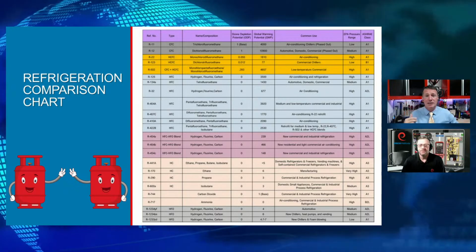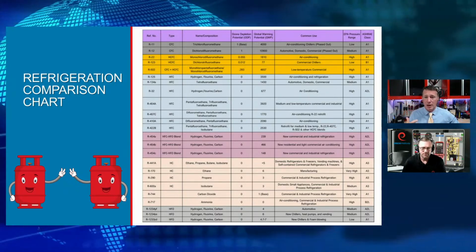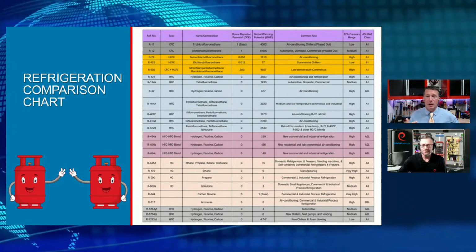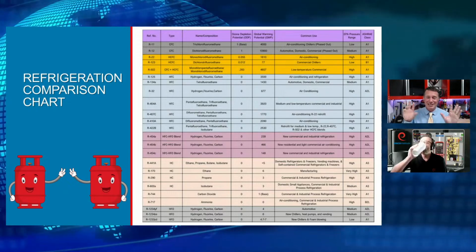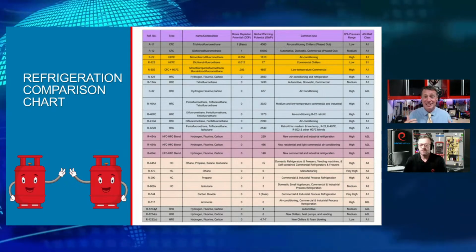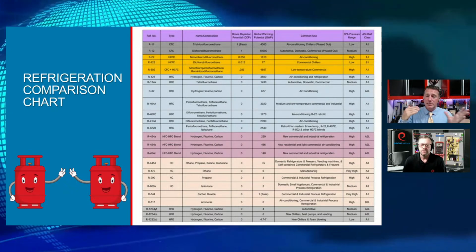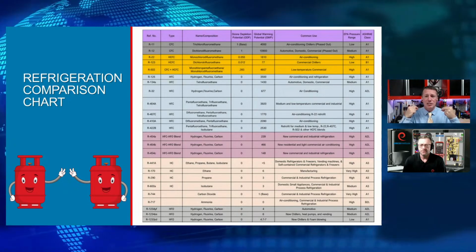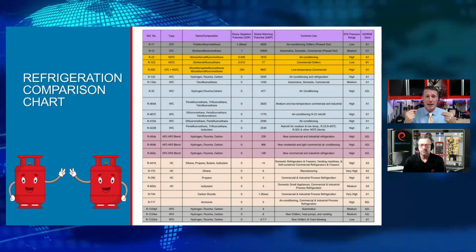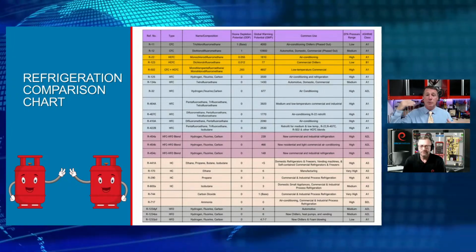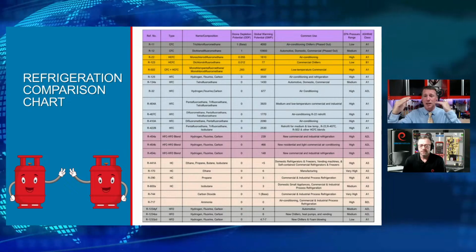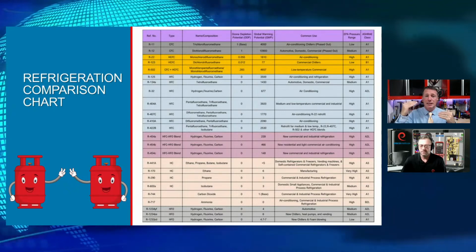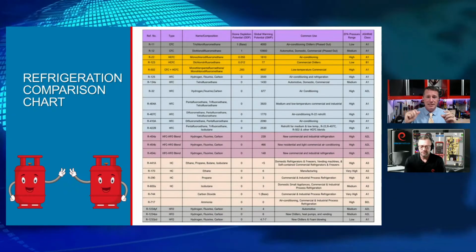If we step way back, go all the way to the top of the chart, up there in the gray, right? That's where we started this entire refrigerant transition away from our Freon classes, right? So Freon is a wide range of refrigerants that falls into these synthetically made chemicals. When we started on our R12 and we started making our descending changes in chemicals, it was to reduce our ozone depletion, right? So we started with our very high ozone depleting refrigerants. We started knocking those off. We came up with replacements for those. So we went from our CFC refrigerants, and we did have some of our HCFCs at the same time.